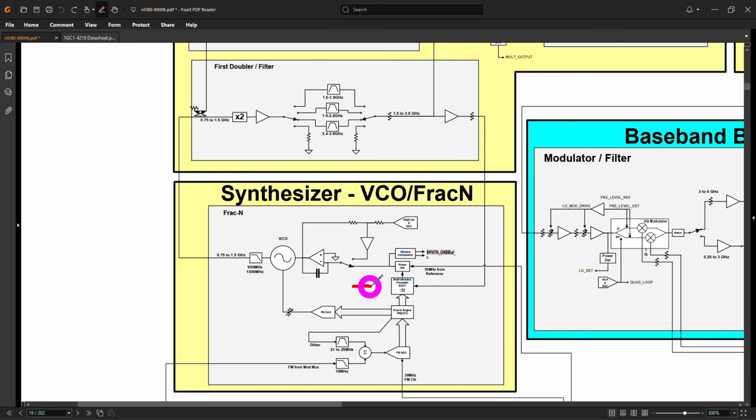So now we did verify that this fractional N divider, at least at 1.6 gigahertz, produces the correct 50 megahertz output, even though the entire synthesizer doesn't lock at that frequency, and that says something potentially, at least at that point. We also looked at the output frequency, 50 megahertz. We saw that we could move it. We looked at both of the tones at the same time. So all of that looks roughly okay.